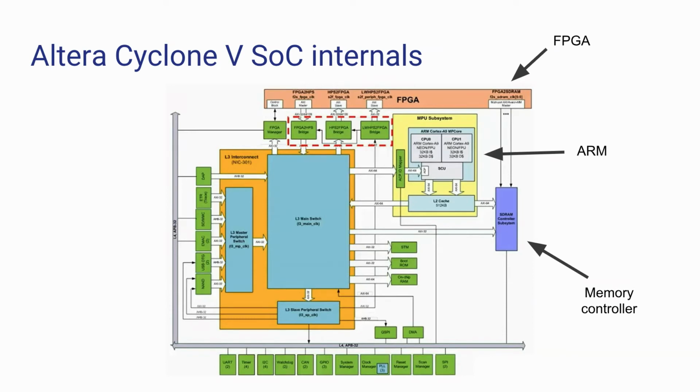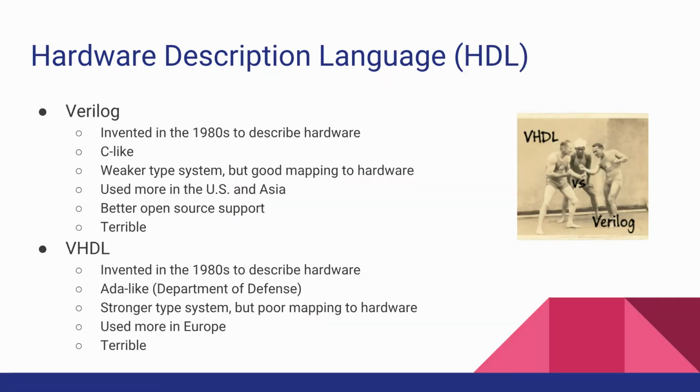And I have some friends who are using a chip that does not have that. Keith is doing this, and he has to interleave memory access himself. He has to make sure that these different parts of the FPGA don't clobber each other. And if you initiated a write, you have to wait for it to come back before you do a read. You don't want to do that. So the memory controller was amazing.